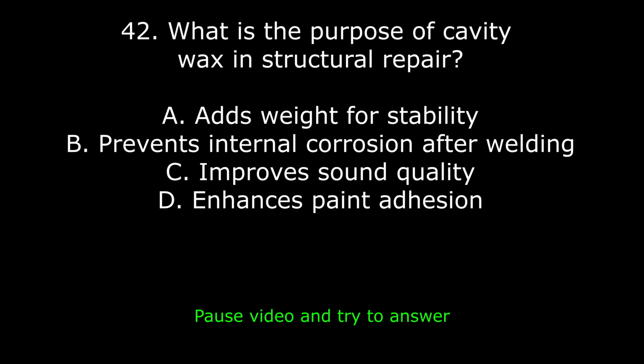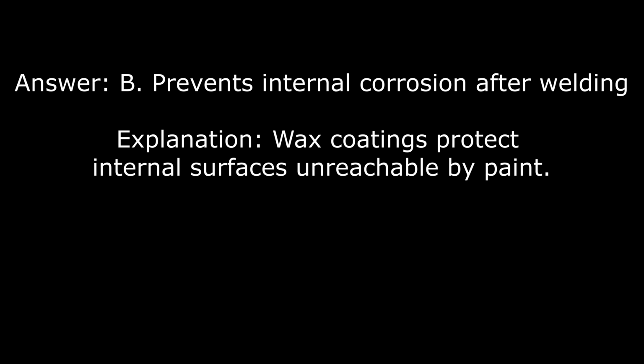42. What is the purpose of cavity wax in structural repair? A. Adds weight for stability. B. Prevents internal corrosion after welding. C. Improves sound quality. D. Enhances paint adhesion. Answer: B. Prevents internal corrosion. Explanation: wax coatings protect internal surfaces unreachable by paint.